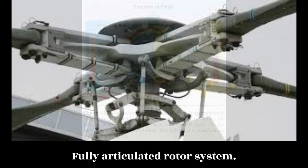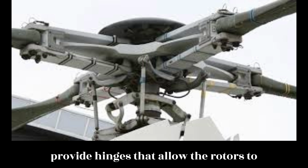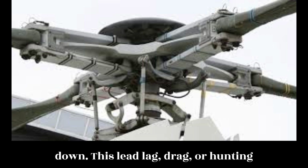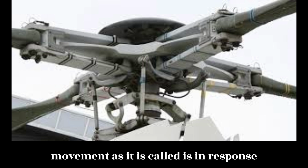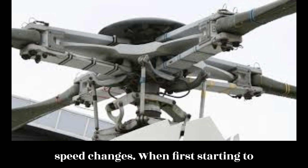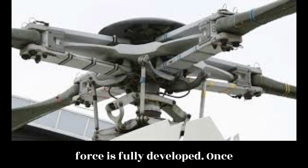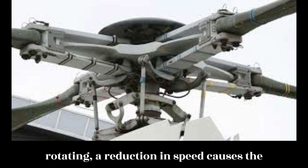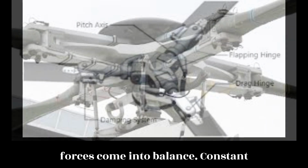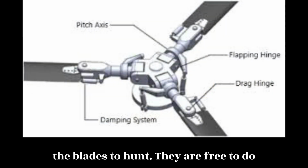Fully articulated rotor system. Fully articulated rotor blade systems provide hinges that allow the rotors to move fore and aft, as well as up and down. This lead-lag, drag, or hunting movement, as it is called, is in response to the Coriolis effect during rotational speed changes. When first starting to spin, the blades lag until centrifugal force is fully developed. Once rotating, a reduction in speed causes the blades to lead the main rotor hub until forces come into balance. Constant fluctuations in rotor blade speeds cause the blades to hunt.